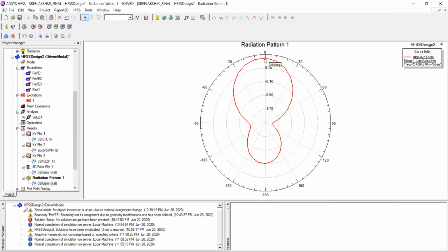This is the main lobe, and here you can see 1.28. That is the maximum point which is coming at the 0 angle. 1.2879 dB is the gain that we got from the 3D pattern also, no? Yeah, that we are getting here. So next we have to find the beam width, like how much area the pattern is covering, or the antenna coverage.